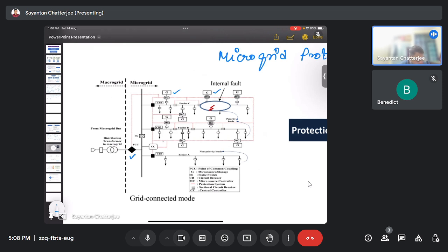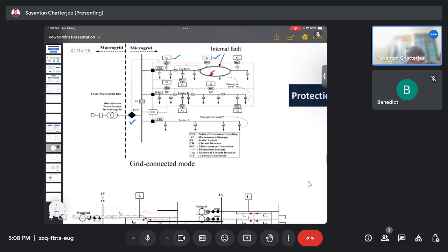Since the DGs were absent, the power flow was only in this one direction, and no breakers were required. The system would also have been easier if the grid had a single DG placed at one end.